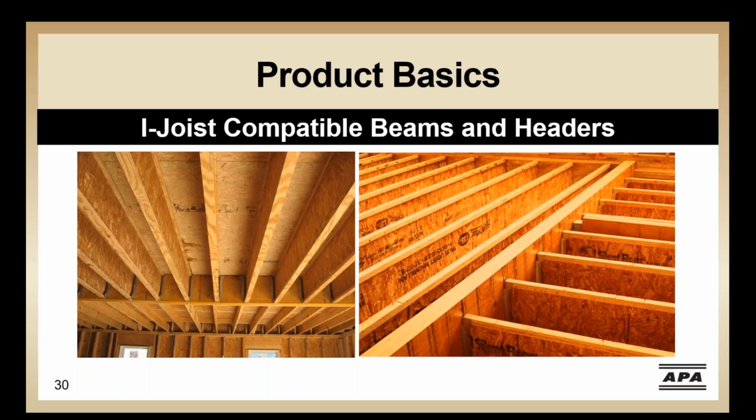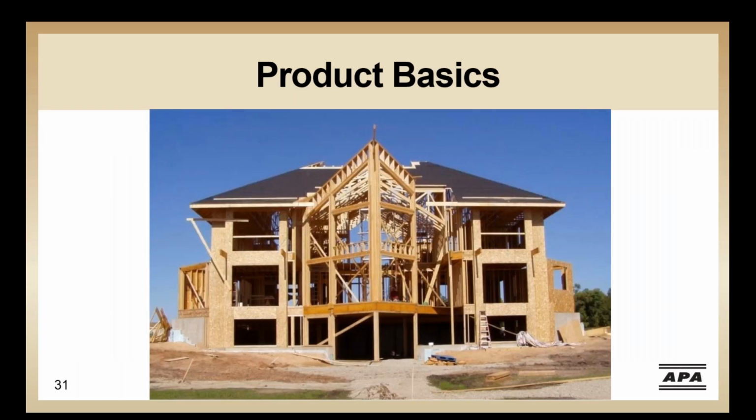So far, we've mostly talked about how glulam and SCL beams frame within a wall system, where glulam beams often match the wall width. As engineered wood floors became popular, it was important for all beam manufacturers to be able to offer products that would be compatible with I-joist steps for ease of framing and finish, because some of the I-joist steps are a little different. Since I-joist manufacturers also manufactured SCL, there was a natural alignment with the joist depth offerings. However, I-joist compatible glulams to match I-joist depths were later developed and are readily available in all markets today.